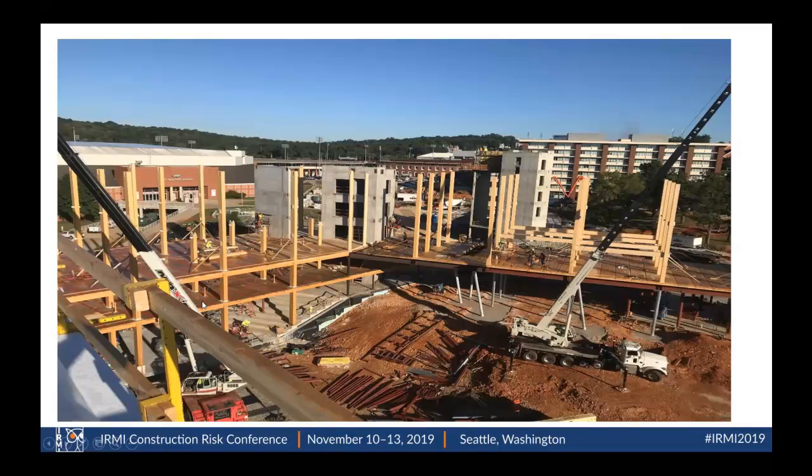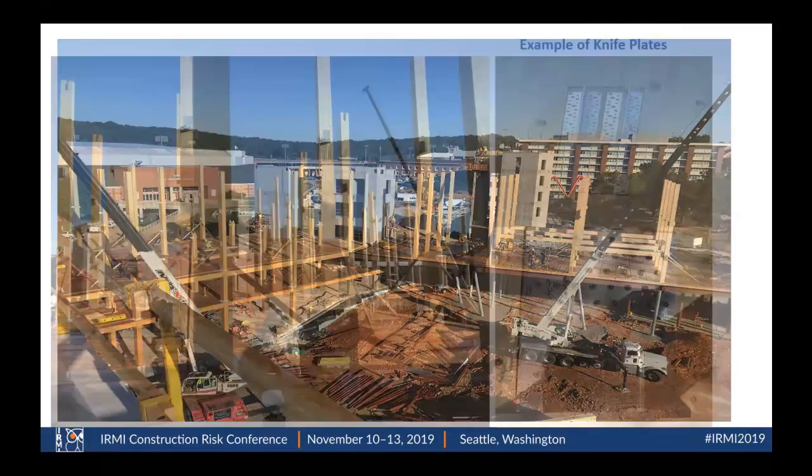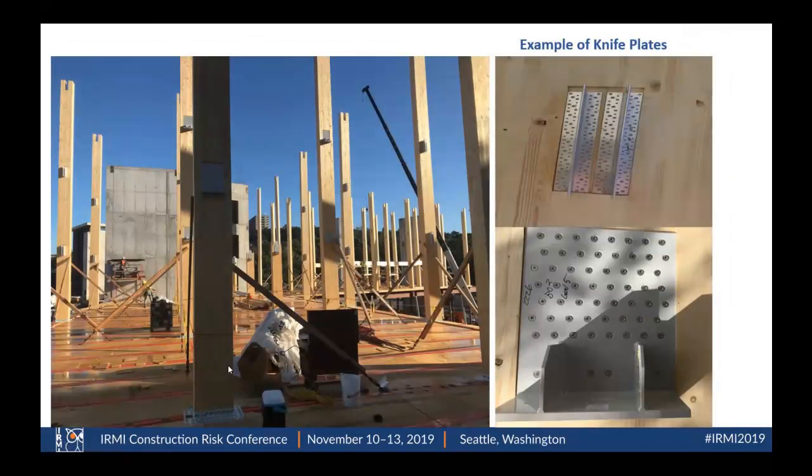When we visited some of the other buildings, we noticed that they had water damage on their columns. So to overcome that, we came up with an idea: we put caulking at the spline joint locations, and then installed the spline boards, and then taped those joints.